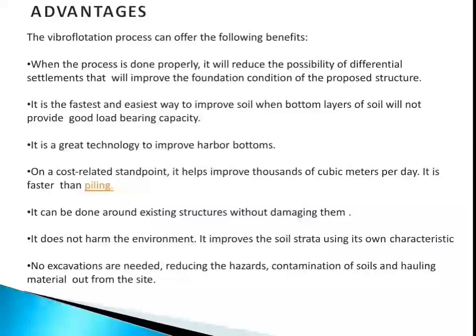Advantages. The vibroflotation process can offer the following benefits. When the process is done properly, it will reduce the possibility of differential settlement, which will improve the foundation condition of the proposed structure. It is the fastest and easiest way to improve soil when the bottom layer of the soil will not provide a good load bearing capacity. It is a great technology to improve harbor bottoms.